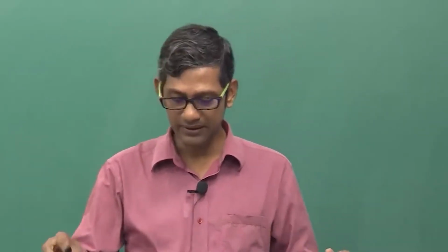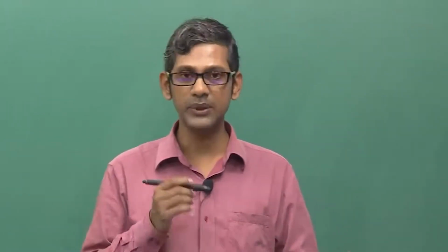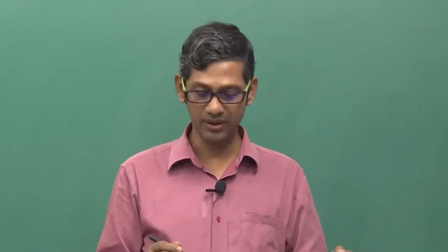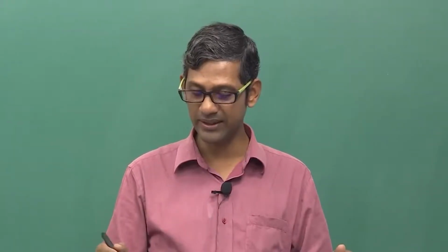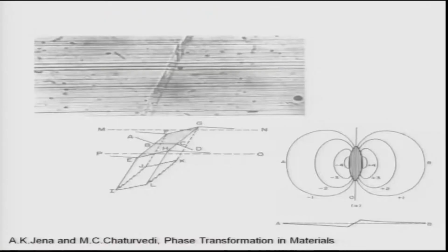Okay, so it is very evident if we calculate, using tools, the strain levels induced both in the martensitic plates as well as in the austenite, and plot them like that. As you see, A stands for austenite and this is the martensitic plate inside it. As is very clear, the strain is on the AB line, which remains flat before distortion or before formation of martensite. After formation of martensite, the austenite is elastically distorted on both sides, and inside the elliptical martensitic plate there is a huge parallel distortion, and this leads to surface relief.